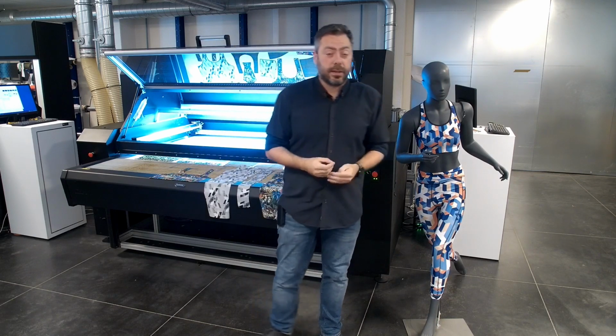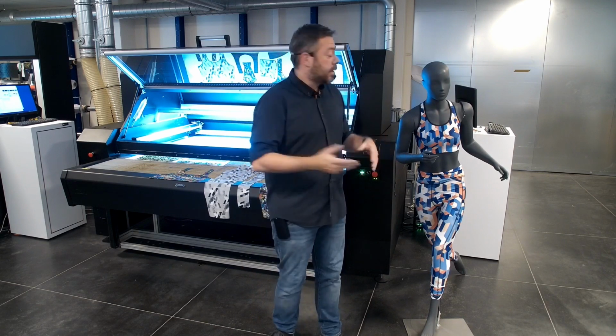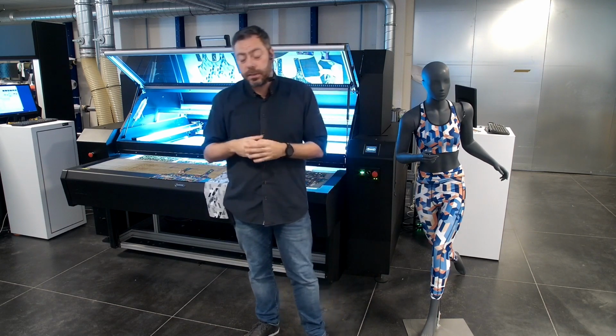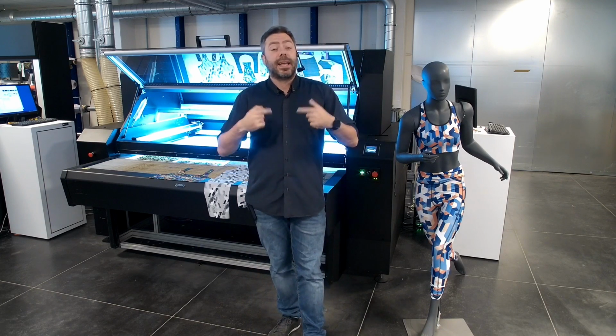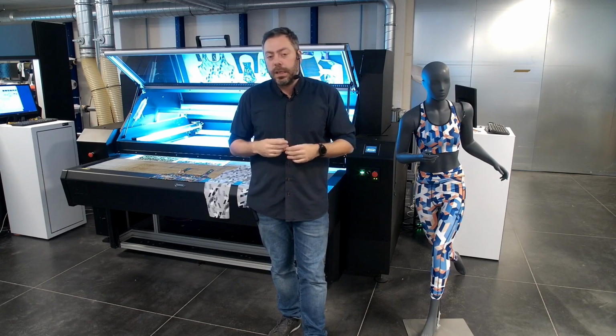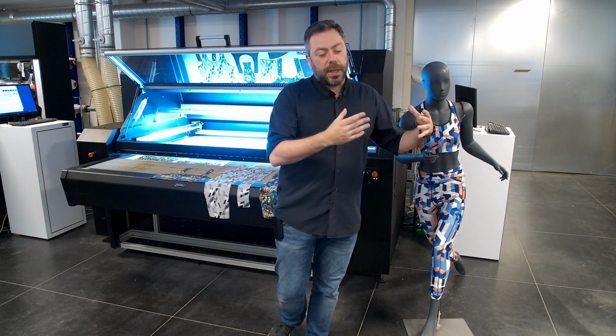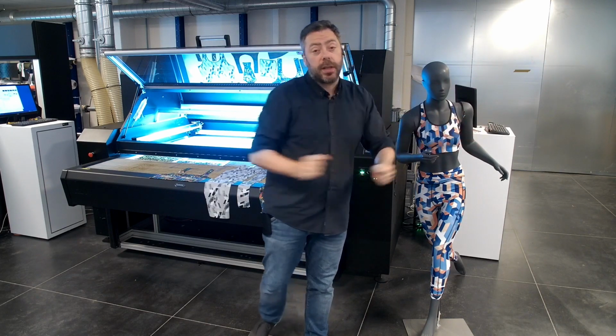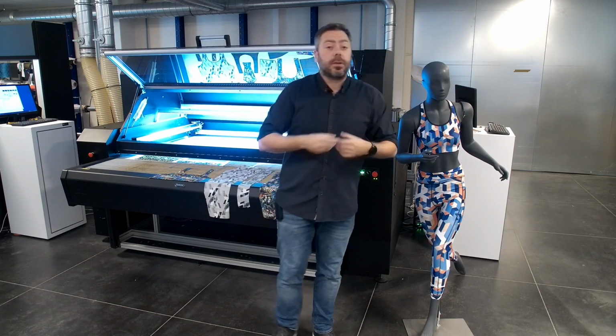So laser itself does cut many textiles. It does give a lot of advantages, especially on the synthetical textiles. If you look at synthetic textiles, especially the dye sublimated textiles, one of the major advantages that we provide is that the edges of the materials get sealed. So this advantage that we have with the laser, where the edges are sealed compared to standard knife cutting, is that it's going to be easier to transport from cutting to sewing without having the material fray.